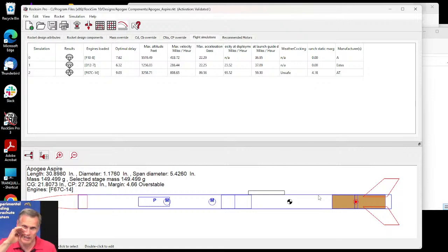At the smallest point, the velocity of the gases is Mach 1. You can't get it any faster than that by converging, but you can get it going faster if you have a diverging section, so it's getting bigger. So as it goes through the choke point, it gets to Mach 1, and then the nozzle gets bigger, and the speed of the gases becomes faster, and that's what you want.